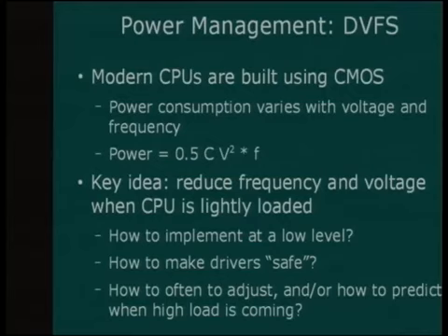The weird part of this is now I'm handing to a programmer essentially a screwdriver to the potentiometer to the voltage on the CPU, which is never a good idea. The question is, how do you make drivers that do this safe? Like when the guy's testing and he has some floating point arithmetic error and he starts blowing zeros or all F's into these registers, you don't want the CPU catching fire and letting out the blue smoke.